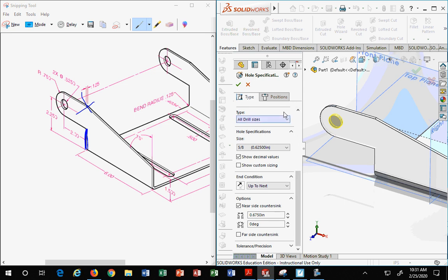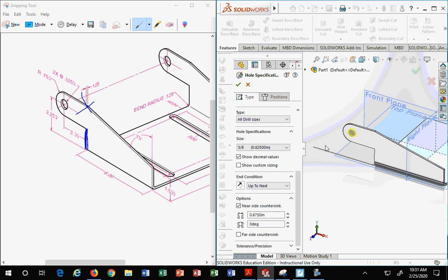Couldn't you draw the other side and just put a hole through both? I can, but that's not how we physically would build this. I would punch everything out, laser cut or plasma cut, whatever it is, in the flat. I would never add a hole after it's formed unless I made a mistake. That's a bad move from a production perspective.